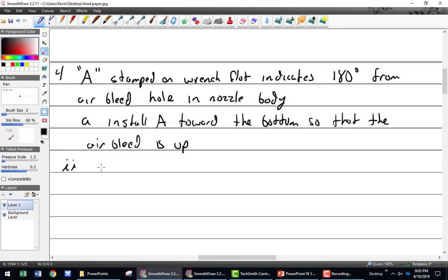This is kind of way out. Flow test. One of the things that you actually have to do quite often as a mechanic is do a flow test. Whenever somebody is having problems with their engine, it's a rough idle, and you've already properly set the idle mix and the idle speed, they have mismatched CHTs or EGTs or any sort of problem, one of the simplest tests to do is a flow test.